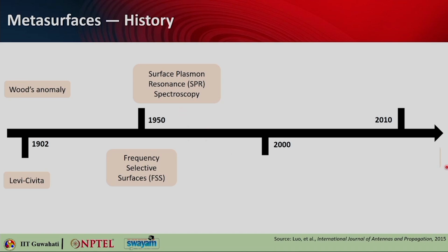Indeed, it will also be shown that SPP and ordinary electromagnetic waves in metasurfaces can be deduced to form a unified theory. So it is basically difficult to separate FSS and metasurface from the perspective of electromagnetic interactions, since both of them can be well described by effective medium theory, effective impedance, and all these things, although FSS is only intended to do some frequency dependent transmission and reflection.